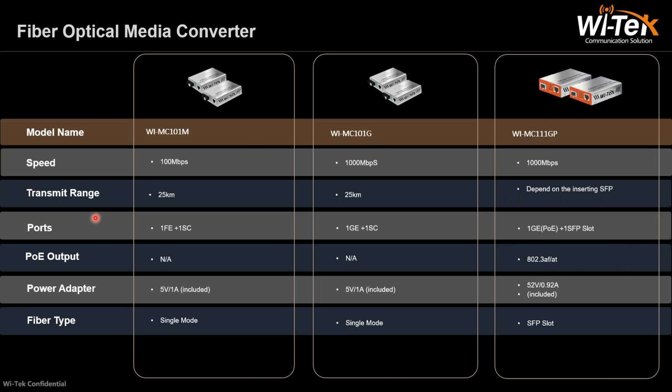Okay, let us quickly review this. It supports a maximum transmission distance of 25 kilometers, and this depends on the SFP, maybe 3 kilometers, 10 kilometers, or 20 kilometers. It all supports single mode.